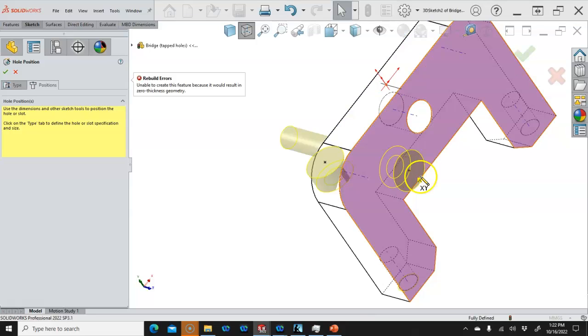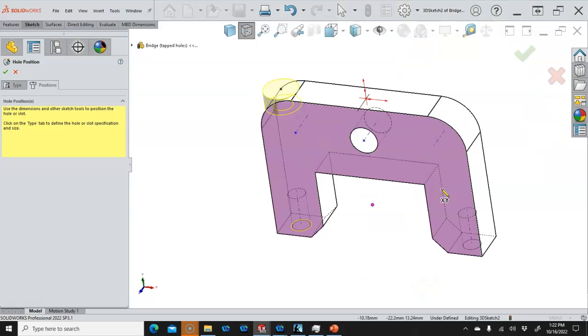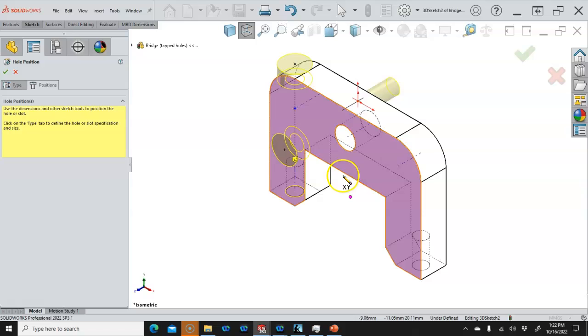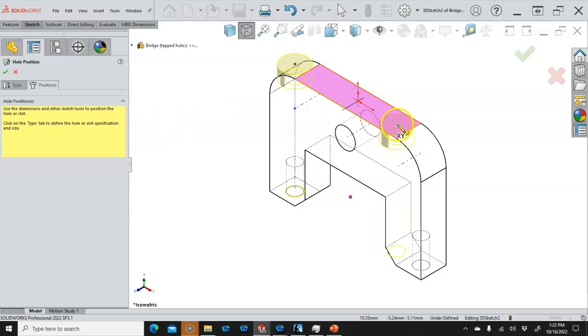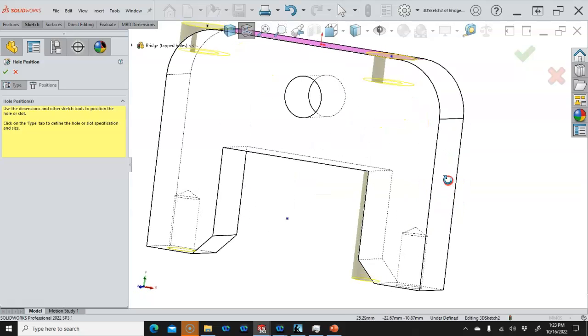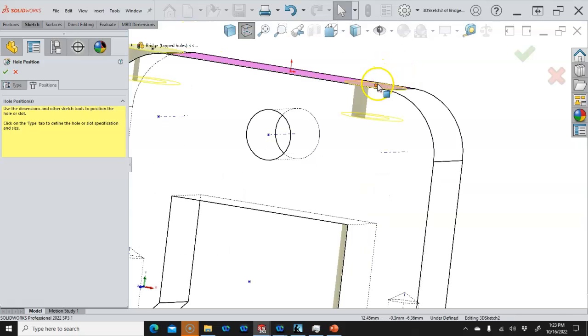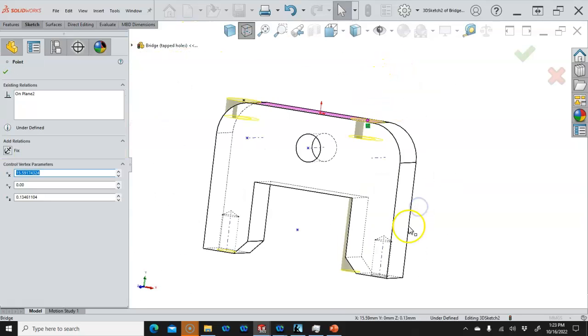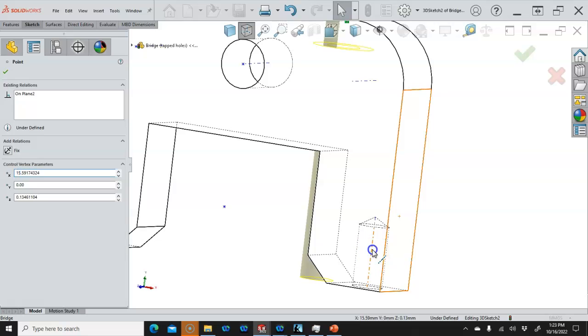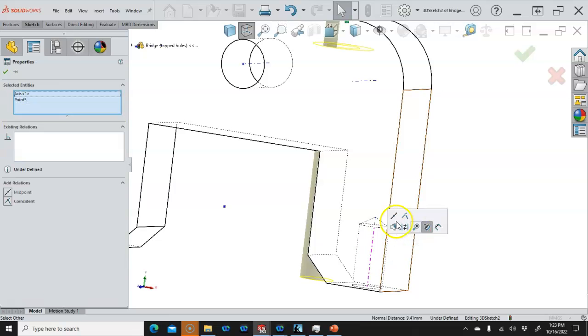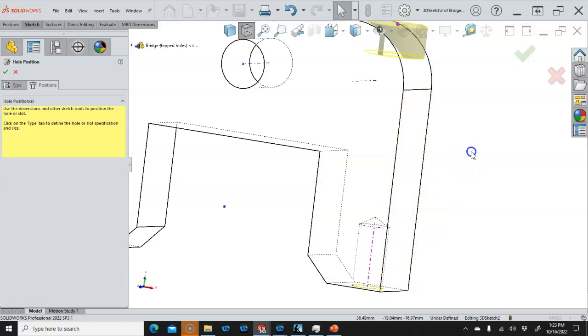All right, so maybe the advantage of the 3D sketch is I can just go around putting 5mm through holes everywhere, but really it's not overly convenient to work with. So I would say stay with the 2D sketch wherever possible. If you see that 3D sketch, make sure you pick your planar face and locate it.